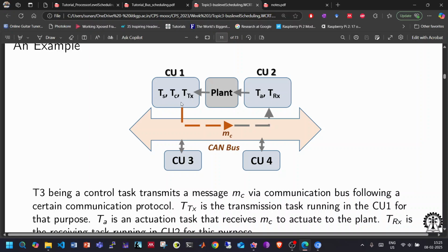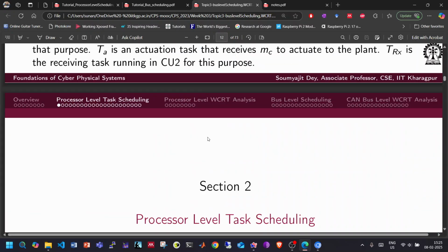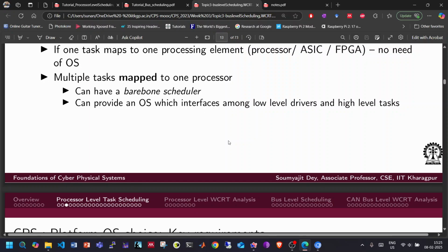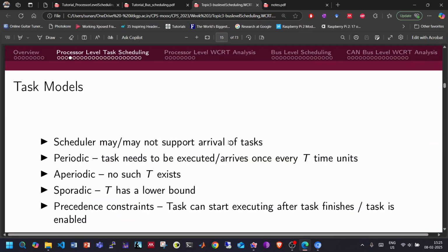Basically you know which tasks will run, because the designer knows what are the things to run after how long an interval. So those things are all pre-scheduled. Okay, so these things are decided beforehand. There are different kinds of schedulers to handle these things. There can be a scheduling policy that helps you understand how to handle a new task arrival. There are policies for that, but we'll talk about them later. First, we'll start with something very static.